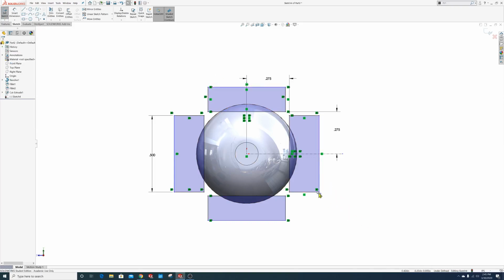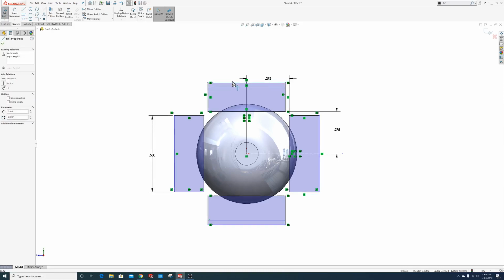Now, in this case, because it really doesn't matter what these are doing, it doesn't really matter that it's underdefined. As long as these lines right here that are doing the cutting are black, we're defined enough. So here's a rare case where it really doesn't matter if you are underdefined. I literally could stretch these out more, but you can see that if I stretch these in and out, as long as I don't come in too close, it's not going to change what's going to be cut off at all.